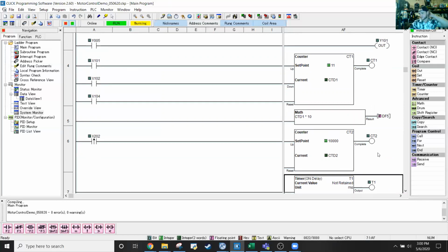All right. So just a little bit more background on this. Basically, what we're programming right now is a very simple encoder. There's a specific hardware module that you clamp onto a shaft, and as that shaft spins, it sends a signal to the PLC that the shaft is spinning, and it gives it a number of counts. Most of them are set up to where you might have 1,000 counts per rotation.